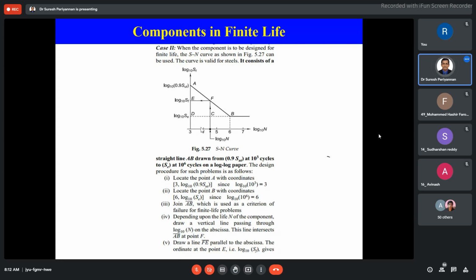We are going to use this standard SN diagram now. I can say two ways. The standard material may go through the fatigue test, or else the same model may go through the fatigue test in the laboratory, because I would like to generate the standard data. Now, the same material I am going to use to design, and once I design the component, I apply it in the actual applications. Once I am applying it in actual applications, we know the number of stress cycles.